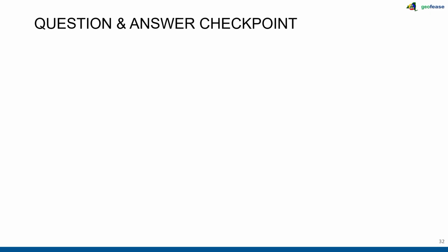Yeah, really good point. So it's early days. I had the opportunity to be involved in the CSA 448 standard development, and that's a binational standard for ground source heat pump systems. And it's early days for monitoring. What we got in there is just a mandatory monitoring of temperatures. Folks thought that it was a burden in terms of costs. However, what we've seen is you can save a lot of costs on optimizing the size of the ground heat exchanger field, which is the most expensive part, right? Drilling those boreholes. So yeah, to answer your question, I agree, but we're not quite there yet in terms of the industry. But hopefully that'll come.